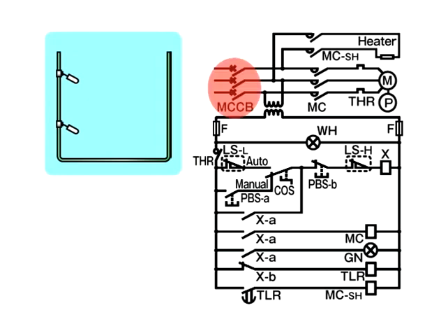The MCCB is turned on. As voltage is applied to the sequence circuit through the transformer, the white lamp WH illuminates, current is passed through XB, exciting the coil of the on-delay timer TLR. Here, TLR's relay operates if no operation is carried out from the time of execution till a set time has elapsed. However, here the pump is operated immediately.